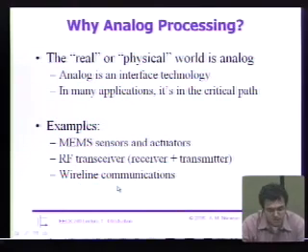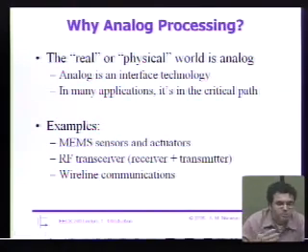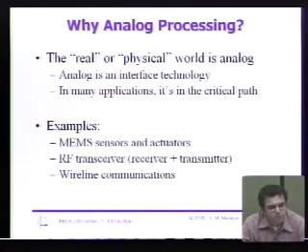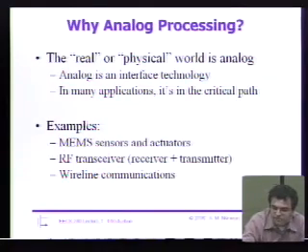So the interface, let's say for your USB 2 cable, or your FireWire cable, or some other kind of link, that's essentially a digital system, right? Why would we care about it from an analog perspective? Well, if you go and look in there, the speeds are high enough and the interface is complicated enough that you really have to understand the terminations, the analog signal properties. You can't just treat it as a digital system.